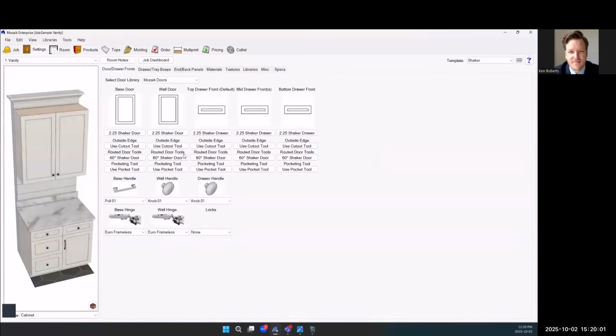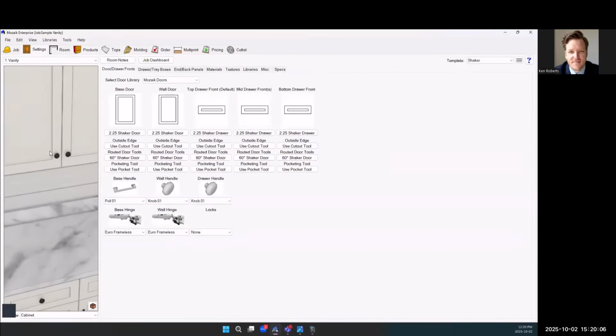Now that we've done a basic shaker and then a bevel shaker, maybe we want to get into something more intricate, maybe shape tools. Maybe this isn't a simple bevel tool or an end mill. Maybe we want to run some beads. So Matt's going to jump in and show you how to draw custom tools and how to apply those to your panel tool groups. Thanks, Ken.